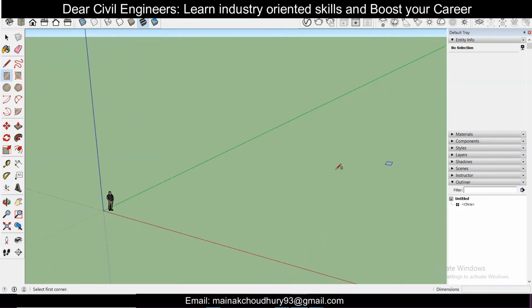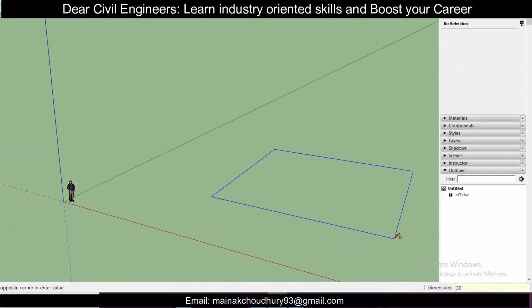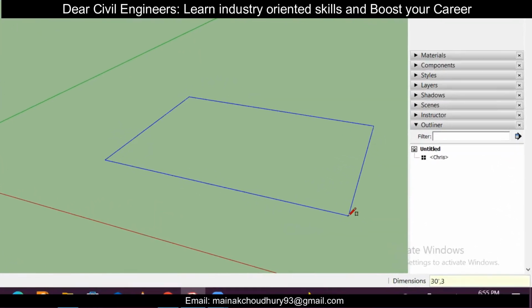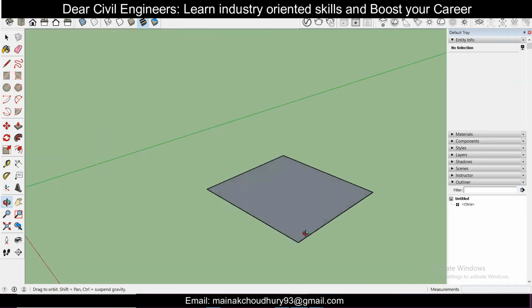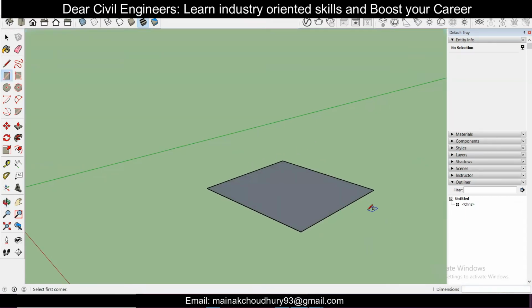First of all, I'll take a rectangle here, and as you know, we are dealing with feet and inches here. So I'll give a random size, just single click on it, and then provide the dimensions. Let's give it a dimension of 30 feet, comma 30 feet, and click enter. So these are the plot dimensions, let's say.